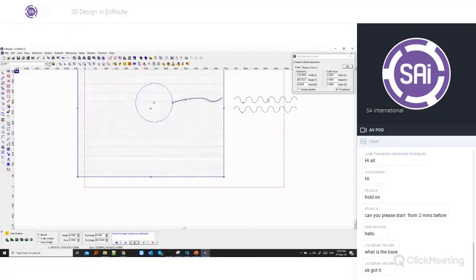We'll choose this as our height control curve. So this will define the height. The more you drag this down, the less variation in height you will get. So I'll choose that like this. And then I'll just go for the width control curve as well. Like this. And once we've done that, we just hit OK.